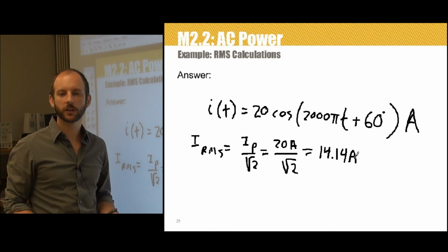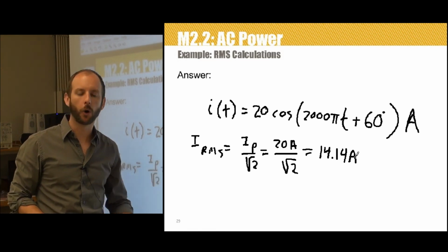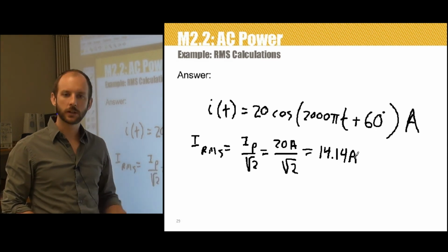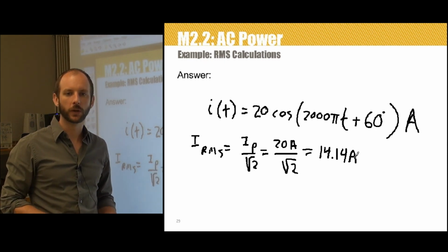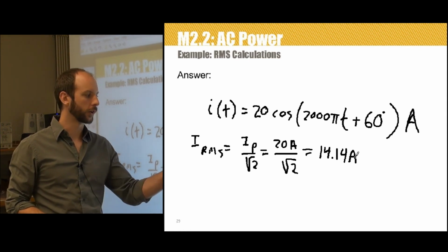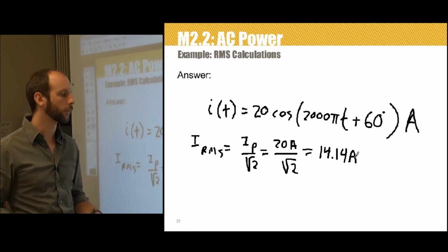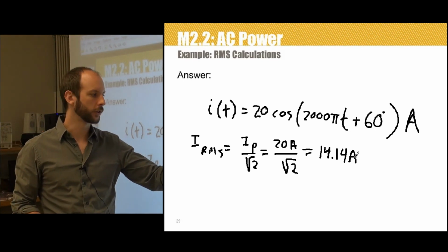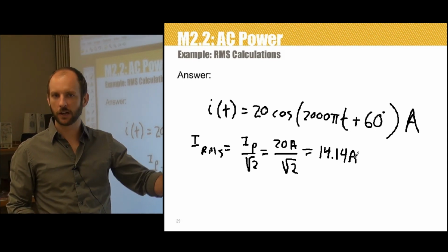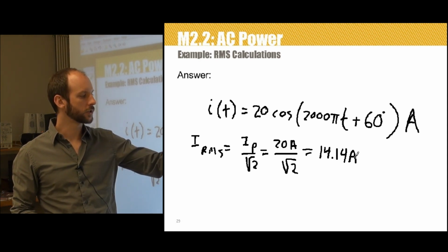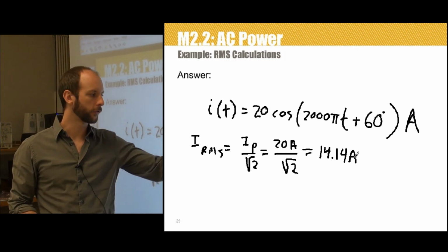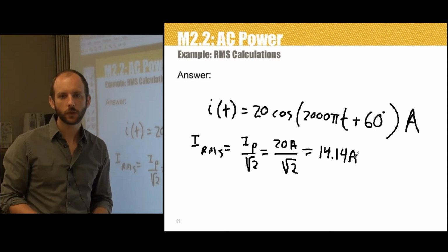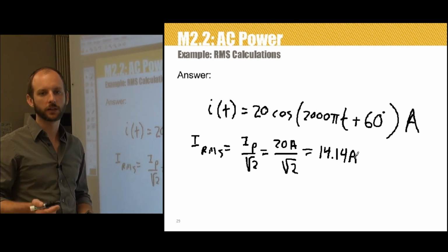For some weird reason in electrical engineering, phase shift is almost always written in degrees, and frequency is almost always written in radians per second, which causes kind of a contention inside the argument of the cosine function. You'll find in signal processing and in other fields, they'll go ahead and put this in radians, but not in the power system. Power system engineers tend to leave that in degrees, and you have to do the calculation to convert from 60 over. So that's pretty easily done.